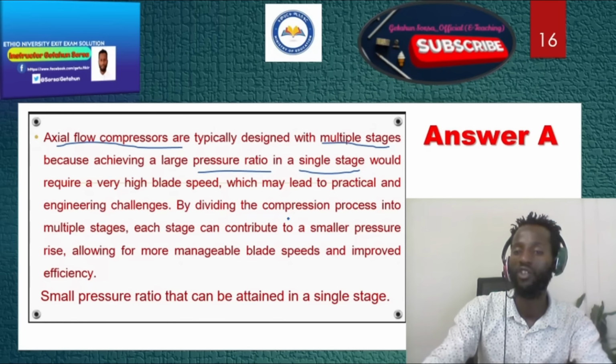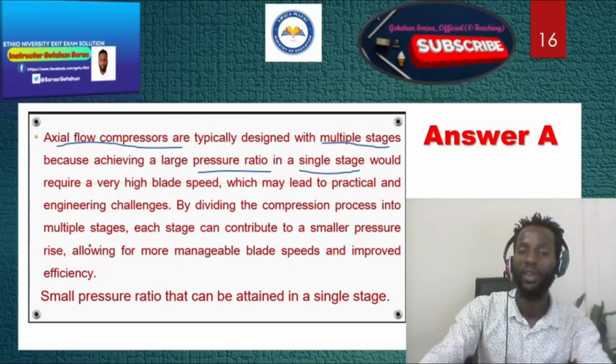By dividing the compression process into multiple stages, each stage can contribute a smaller pressure rise, which allows for more manageable blade speed and improved efficiency. So it is a small pressure ratio that can be attained in a single stage, and to obtain a large pressure ratio, we have to arrange these axial flow compressors in multiple stages. Therefore, the correct answer is A.